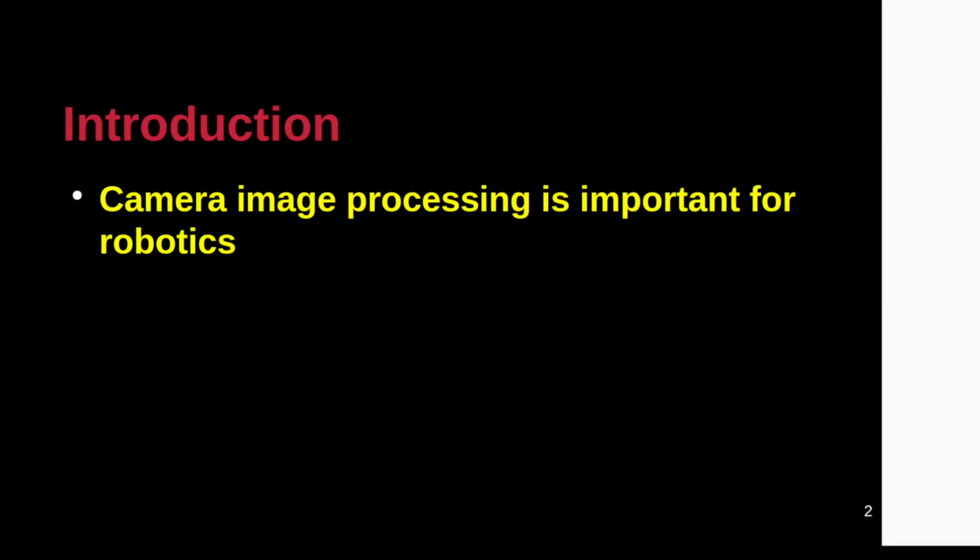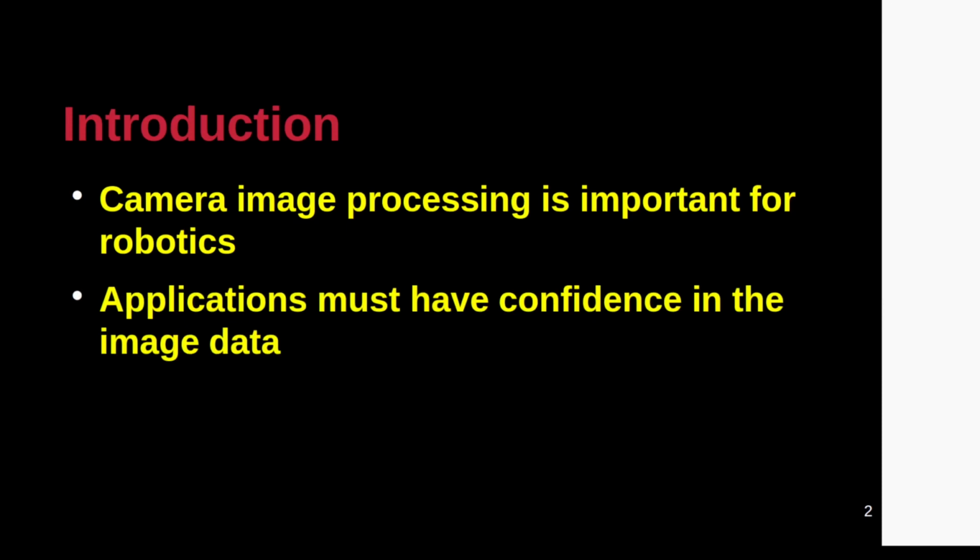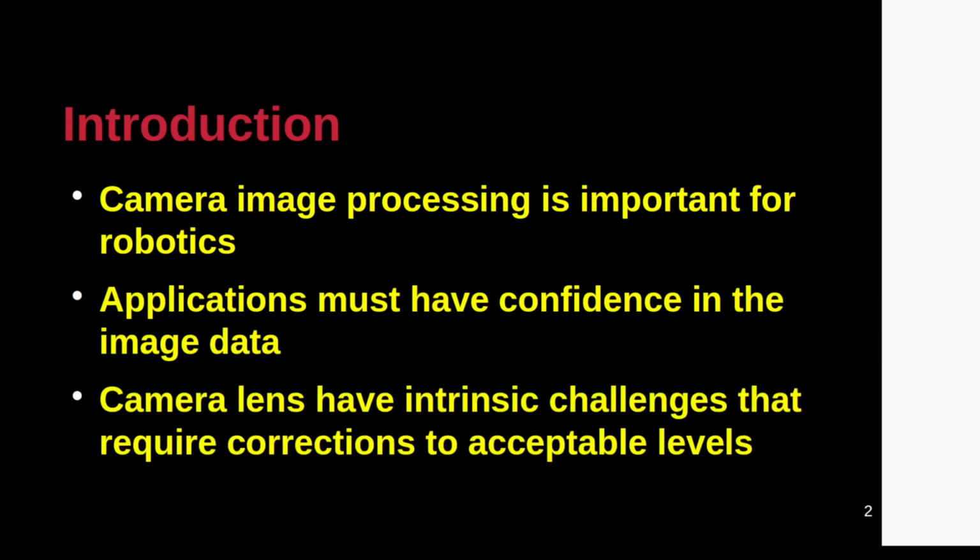Several robot operations, such as moving to a location or recognizing objects, require a consistent degree of accuracy from vision data. The acquired images have to be rectified such that calculations using image data are rendered as hardware independent for use in OpModes. For this reason, cameras have to be calibrated not just to compensate for any lens distortion, but also for the resolution used to acquire the images.